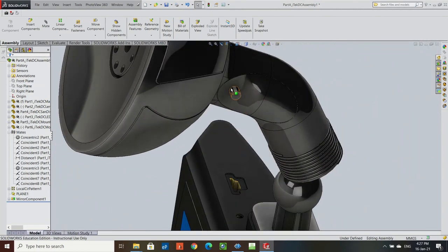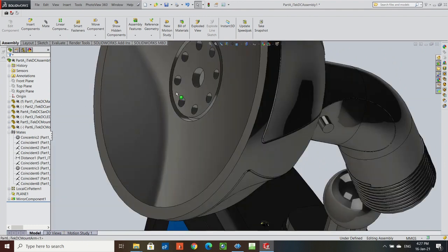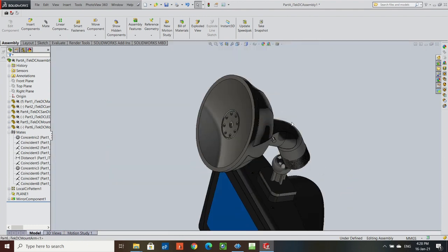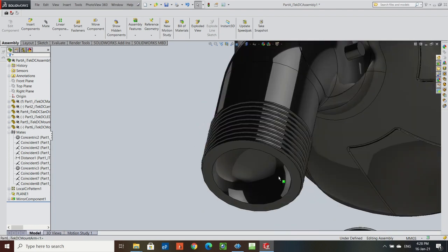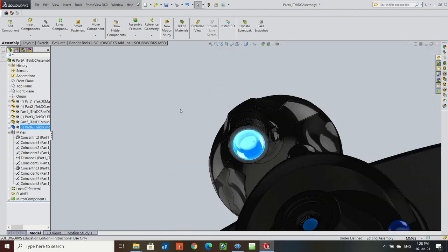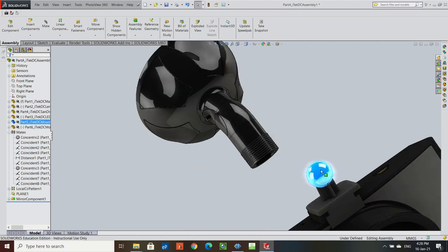Okay, these are for the little clip that gives the impression for the suction to be made with the suction pad on the windscreen. I have thread here, and inside here I have a hollow, and the diameter of that hollow matches the diameter of the sphere here. That creates the ball joint, okay, that allows the camera to move. And there's going to be a lock nut around that; the more you lock the nut, the tighter it gets. The looser, the more you can move it.